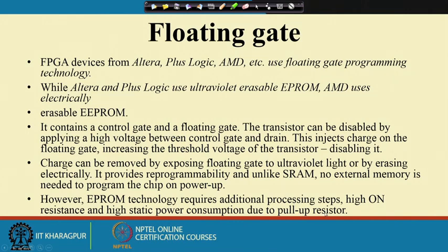So, this is reprogrammable because you can remove that floating gate charge by applying either ultraviolet light or a high voltage, but unlike SRAM, it does not need off chip reprogrammable memory to hold the control program.